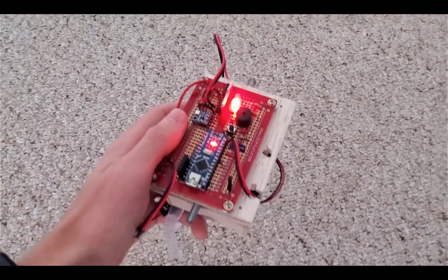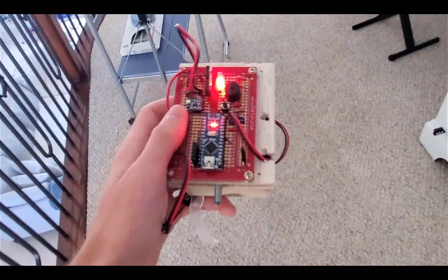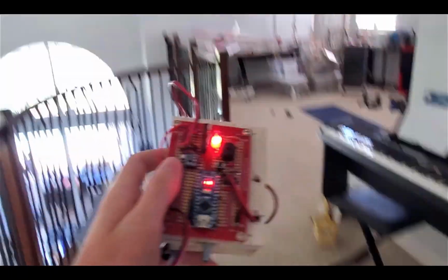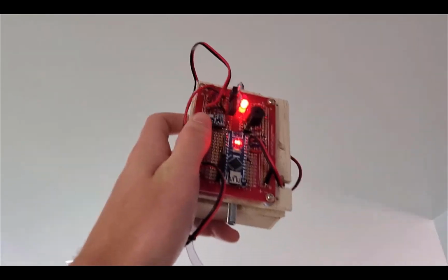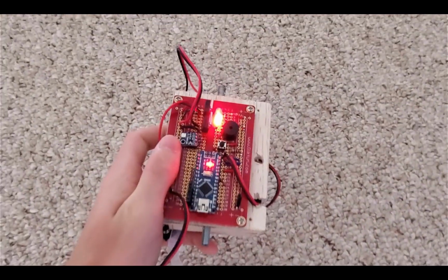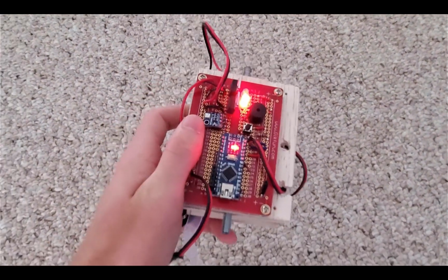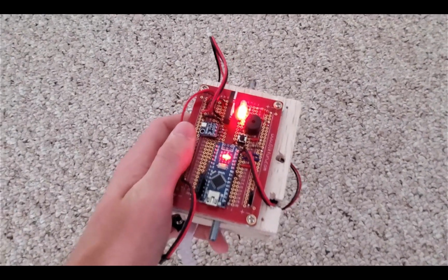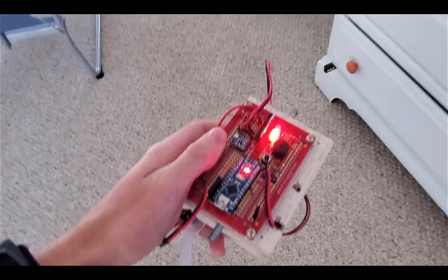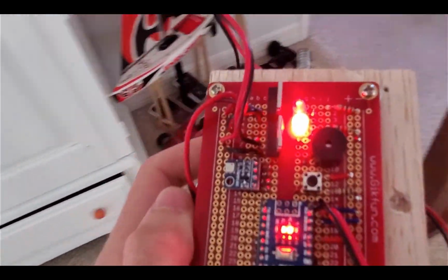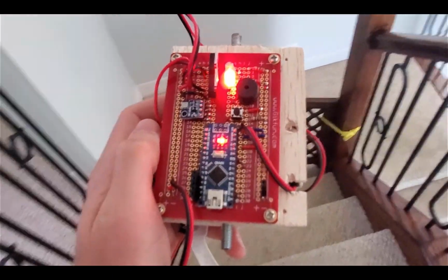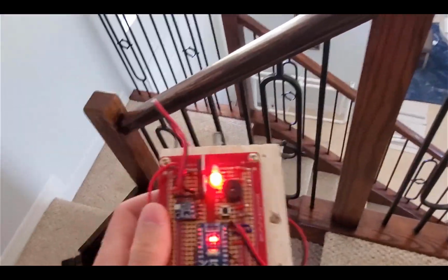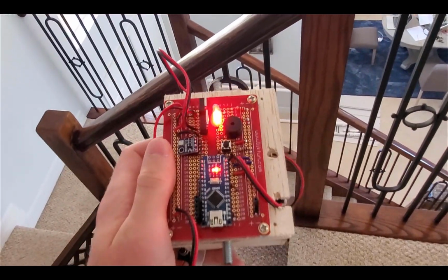So right now the ejection charge would be deploying, and for the sake of redundancy, we have a second ejection charge in there in case the first one doesn't work. And so if the rocket's still going down too fast, it'll go again, just like that. So that's basically what Beep Beep does. Meanwhile, we have the altimeter tracking the data on an SD card, and when it gets to the bottom, it'll stop tracking and everything. So there's a lot more in it, but that's basically what it does.